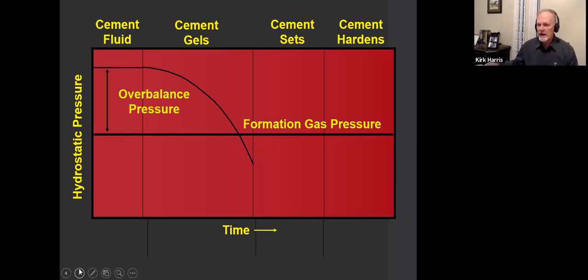Every well that we cement, every well will go underbalanced. And when a well goes underbalanced, it's going to flow. There is more pressure in the formation at that point than in the annular space. After we cement, I hope we're overbalanced and the well is under control. But every well, eventually, the cement will gel. You will have loss of fluid and you will go underbalanced. We just want that to occur before too much gas comes in.